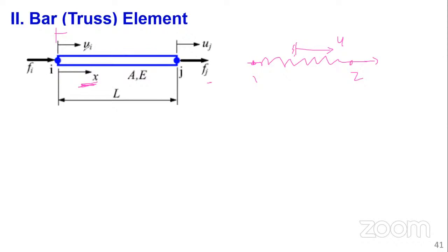So as you look at it, we can have deformation or displacement at node 1 or node I, Ui, and displacement at node J. Then F, the small letter, remember we talked of that. These are nodal forces, internal nodal forces or nodal members. Then now, remember for our spring, the stiffness was just described using K, K being the elastic constant.